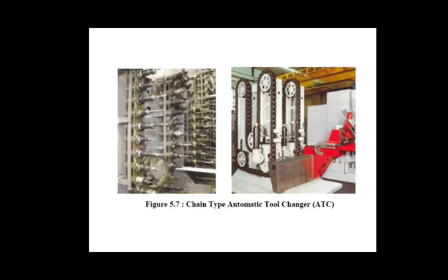We have seen that in a conventional machine it takes many minutes or even hours to change the tool, but here the time required is less, and there is also operator safety. Tools can be changed in seconds for maintenance and repair, and it increases flexibility. Heavy and large tools are also exchanged automatically. These are the advantages.